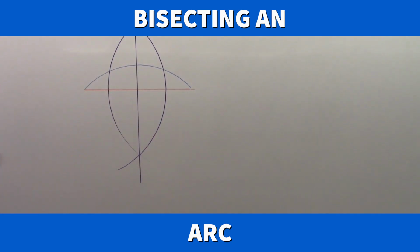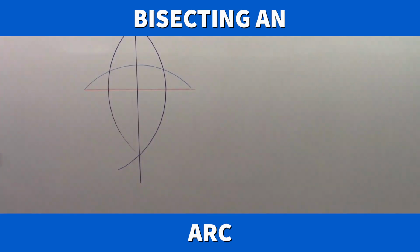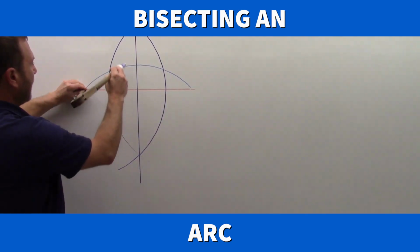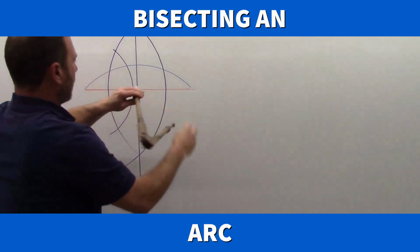It's exactly in half. Now I said earlier that it doesn't matter how accurate your 3/4 is as long as it's past halfway. So now we know where halfway is. If I set my compass less than halfway and swing that same arc, you can see that they don't cross each other.